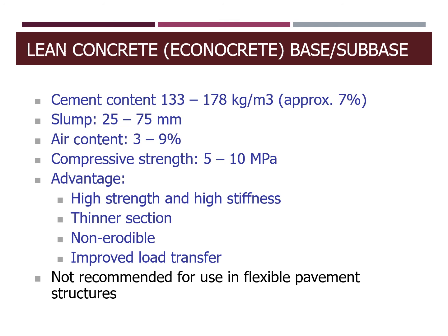However, this kind of base or subbase structure is not recommended for the flexible pavement structures. As you may know, for the flexible pavement, the distribution of the load will usually be concentrated. In that sense, it will easily cause cracks or distress to the lean concrete layer, which will cause some failure of the pavement structures.